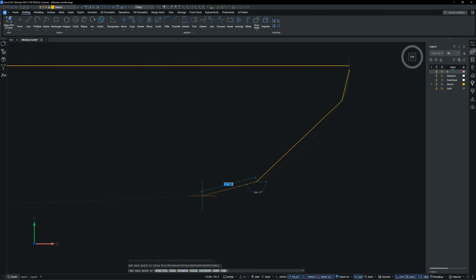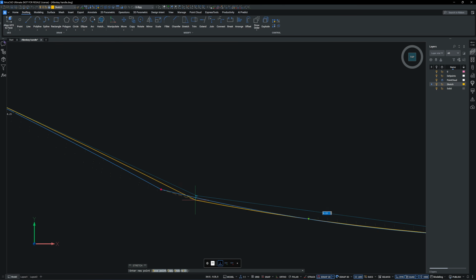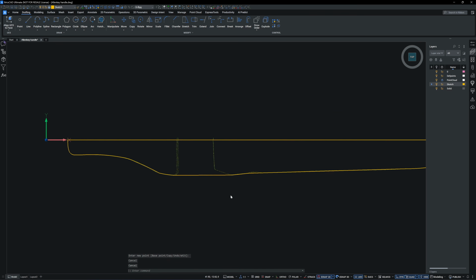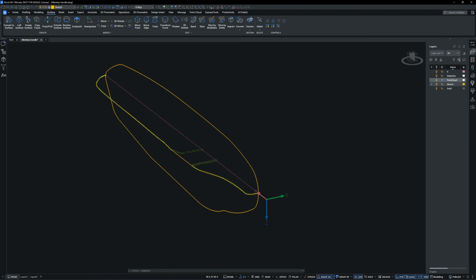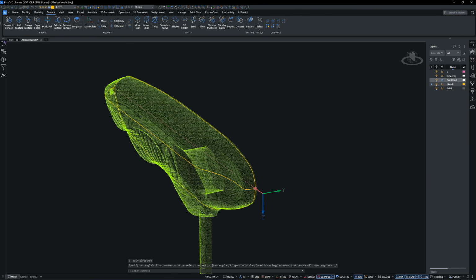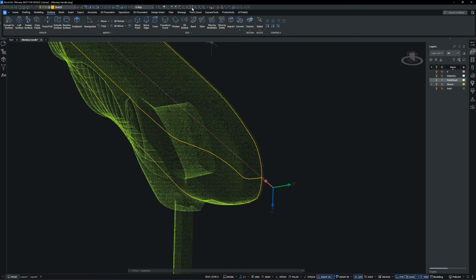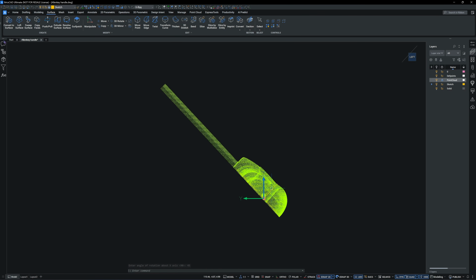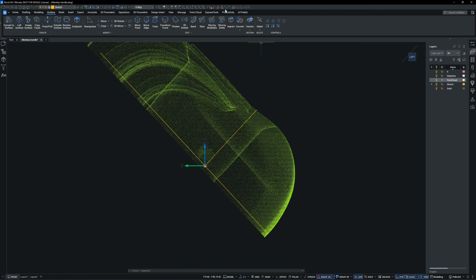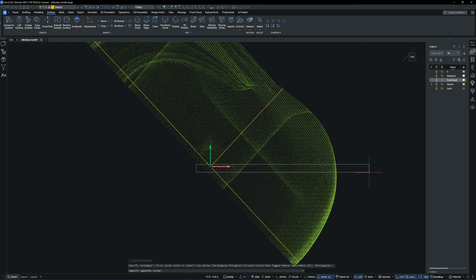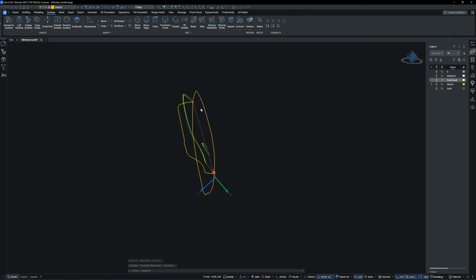I'm not going to demonstrate every sketching step. They are straightforward and you will need to practice them yourself to really learn it. Next, I will rotate the UCS x-axis by 45 degrees to set up the next sketch plane. Then I will crop the point cloud along that plane to create the next cross-sectional profile.